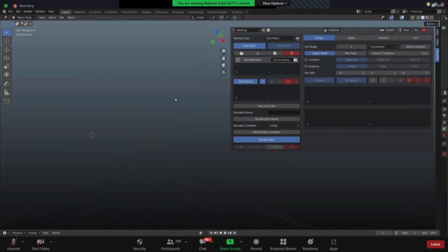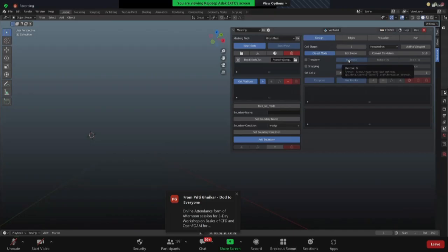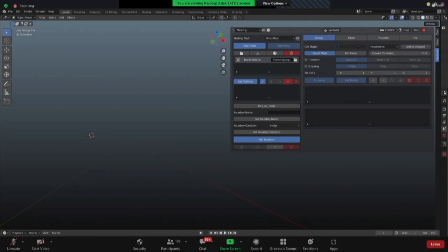So with this, we are yet to start our geometry design. Now I'm going to start bringing the blocks up. If you look at the geometry, you have essentially 3 blocks, if you remember the geometry. So you have these 3 blocks, and I'm going to select 3 cell shapes. OpenFOAM refers to these blocks as cell shapes, so in the GUI, you will see them as cell shapes instead of blocks.